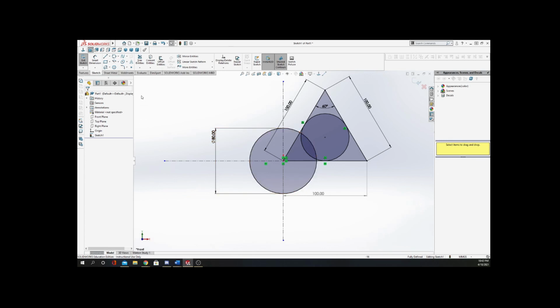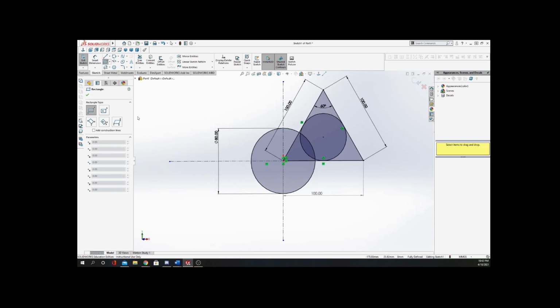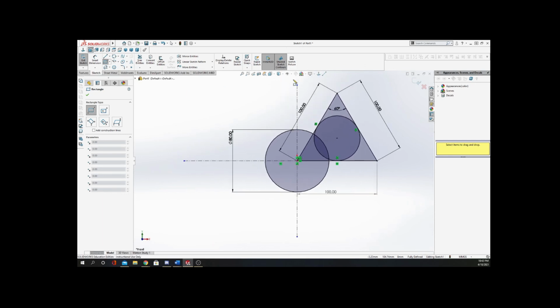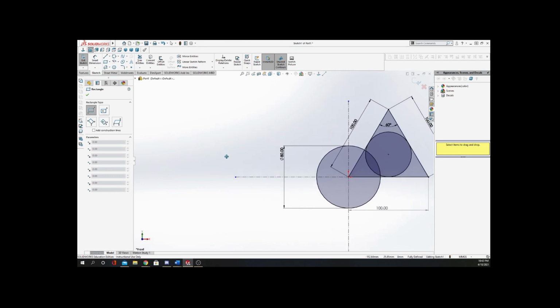All right. So now we'll go on and we'll look at squares or rectangles. So we'll just pick this first one. It's a corner. It's a corner rectangle. And what we'll do is we'll let me go back to being normal to my screen. If you push Control and the middle mouse button down, it lets you pan sideways. If you just push the middle mouse button down, it lets you rotate on these axes. So I just wanted to slide it over a little bit.